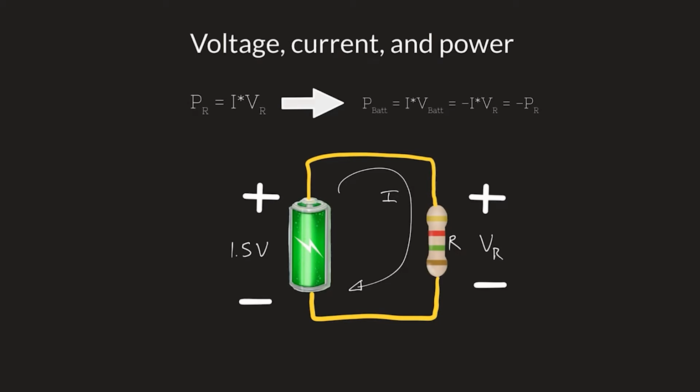So power computation does not involve Ohm's law, or it doesn't have to. As you can see here, the power being provided by the battery is I times V, and there's no Ohm's law involved in that. For the power being dissipated in the resistor, you will use Ohm's law to calculate that. And that's necessary in order to know how much power is being delivered by the battery, or you could just measure the voltage across the battery and the current coming out of it, and you would know that that much power being delivered must be dissipated in the circuit.